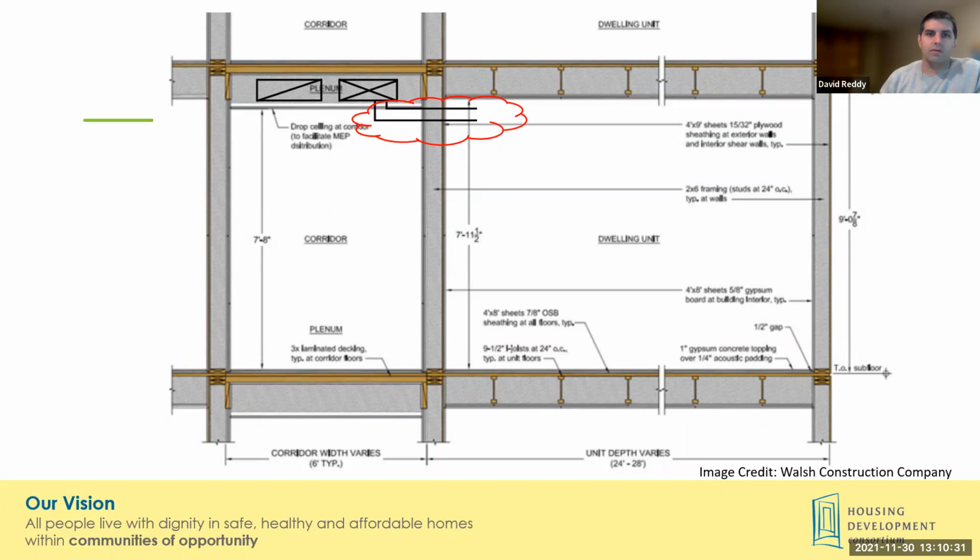The duct getting into the unit from the corridor means the corridor ceiling has to come down, and that really wasn't realistic given it was already at, and this diagram shows 7.8, but I think it was 7.6, and just with other clearance issues, going lower wasn't realistic.